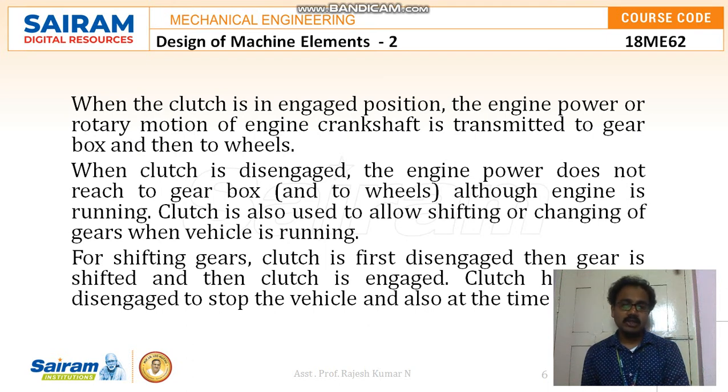For shifting gears also, the clutch is first disengaged, then the gear is shifted, and then the clutch is engaged. The clutch has to be disengaged to stop the vehicle and also at the time of idling.